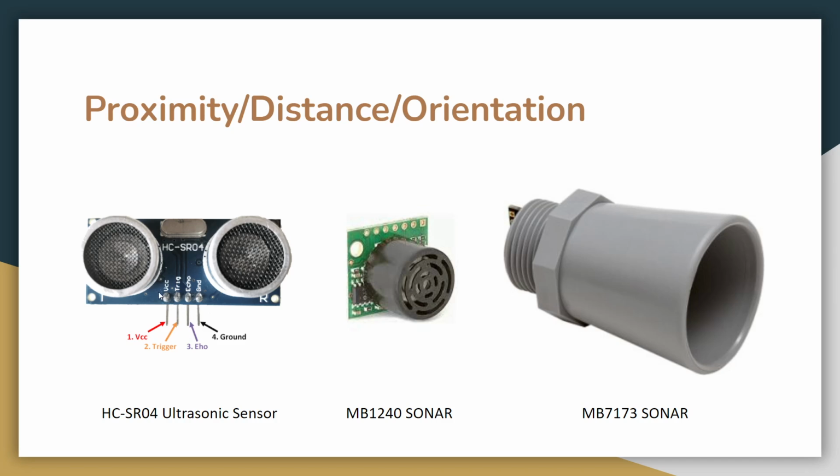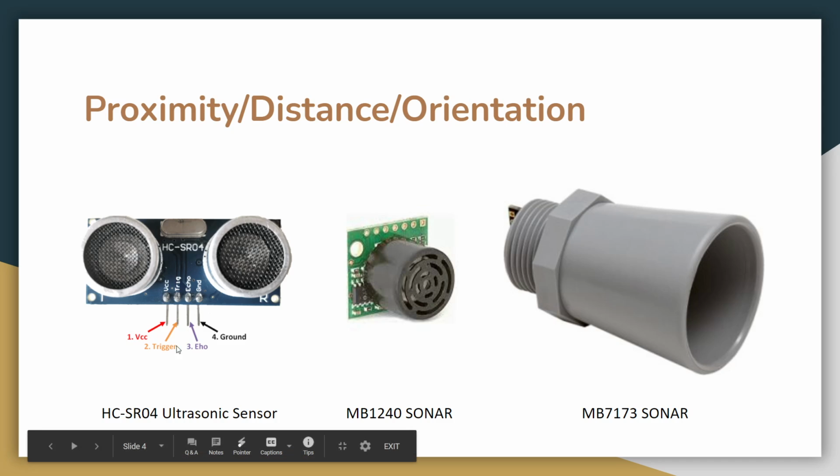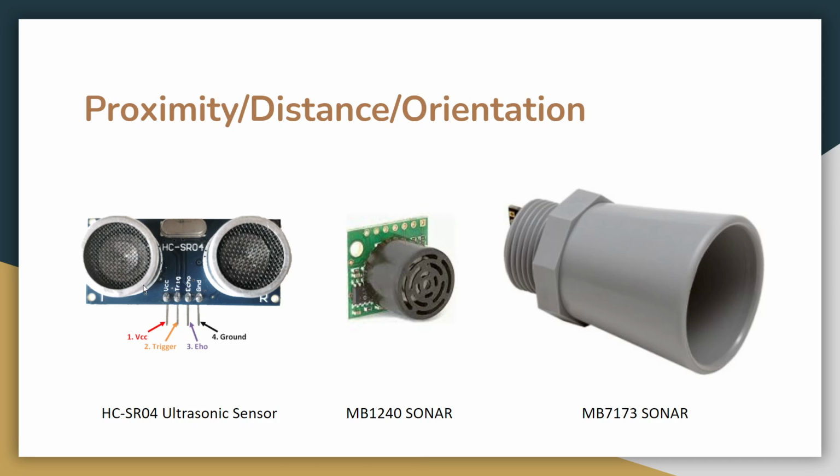So basically, you're going to use the trigger and echo pins with a microcontroller. You signal the trigger pin with a 5 volts signal, and the ultrasonic sound will be emitted from the emitter. Then you have to wait for some time. You should generate a pulse. Basically, a pulse is a low signal, then a high signal, and then a low signal. So a pulse of ultrasound has to be generated, and then the echo will basically be an input pin. The echo receives the reflected sound waves back, and once it receives them back at the microcontroller, you can find the distance.